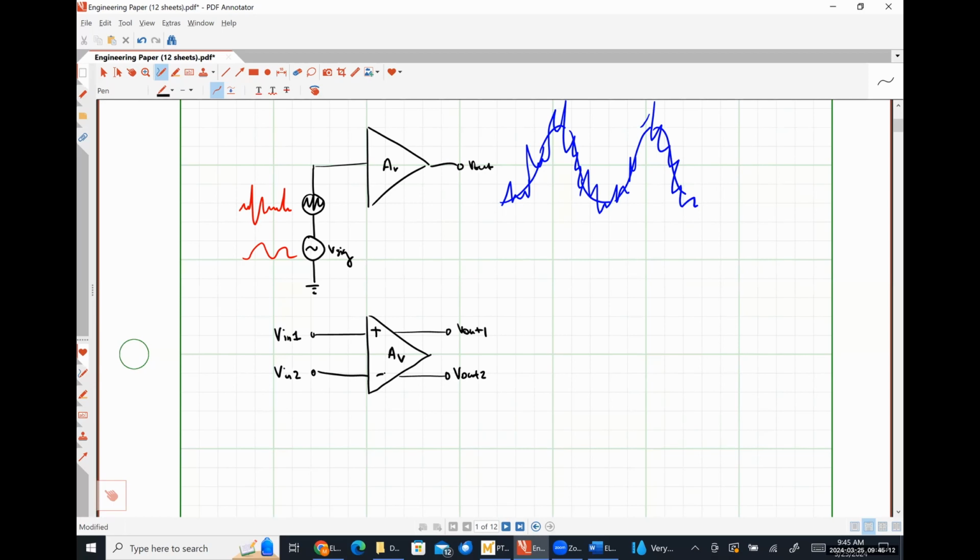So we can literally think of this as kind of like two single-ended op amps, but our output signal could be taken as the difference between those output terminals, meaning that if the noise were applied to both terminals equally, and we took the difference of those outputs, the contribution of the noise would cancel each other out.